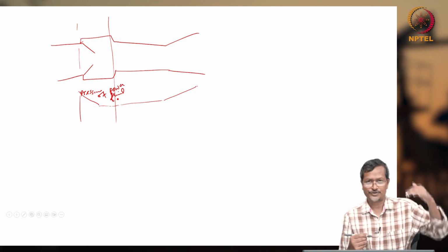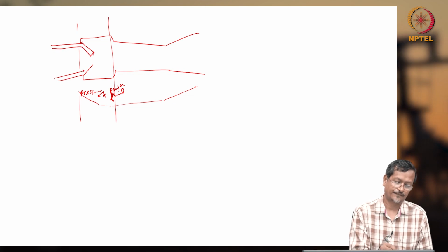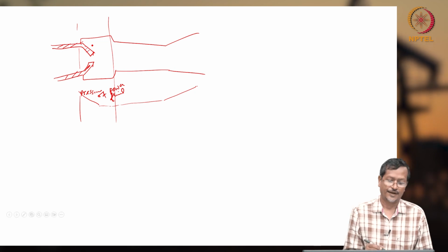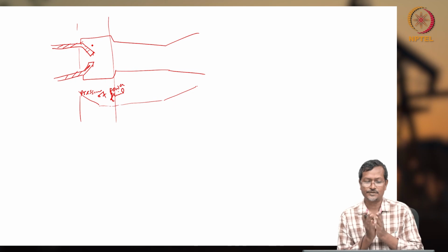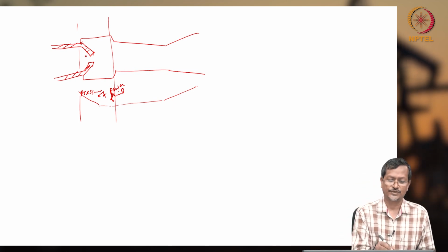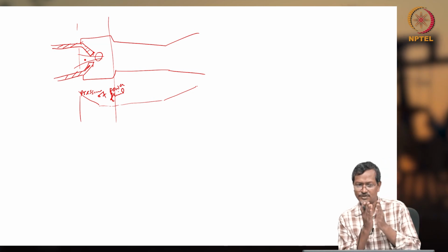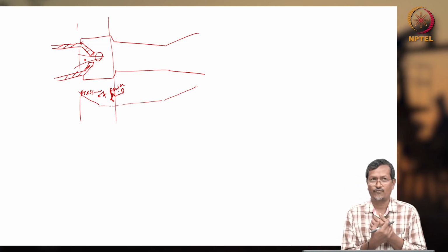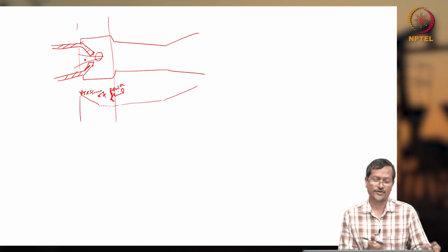Okay, power fluid pressure is initially going down at the nozzle. This is the nozzle section, so nozzle section pressure will be going down. After the nozzle, a little bit more drop will be there, because when fluid goes through this nozzle, the lowest cross-sectional area is created just after the nozzle, which is called the vena contracta area. The vena contracta area will have the lowest pressure, so the suction rate will be higher.